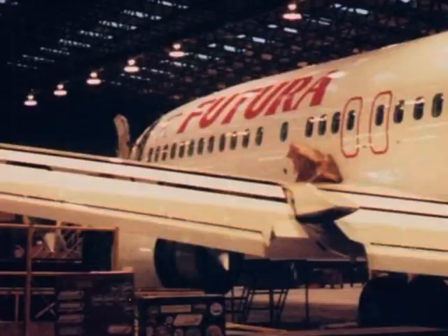The triple slotted Fuller flaps, once extended to the full extend position, which is 40 degrees. If we look at the trailing edge flaps, there are three panels, and they are the fore flap, mid flap and aft flap. Between the fore flap and mid flap, between the mid flap and aft flap, and between the fore flap and the trailing edge of the wing, we have three openings, three ways. Because of this, it is called the triple slotted Fuller flaps.